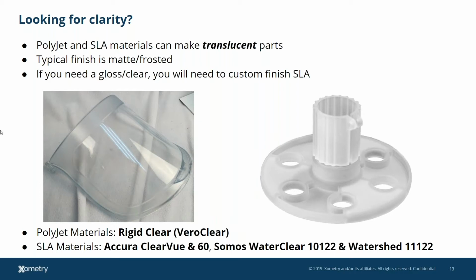But if you want something that looks more like this face mask on this side, you're talking about somewhere around $800 to $1,000 of labor. This is essentially polishing your headlights on steroids. You're taking a part that comes out inherently frosted, but on the inside is clear through, and you're doing a full surface treatment, often with clear coats and different hand finishes, moving from maybe a 400 to 600 to 800 to 1200 to 1800 to 2200 to 2600 wet sand to bring that grit down to get a high polish out of it.